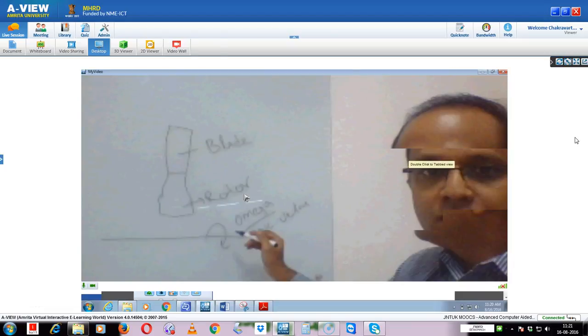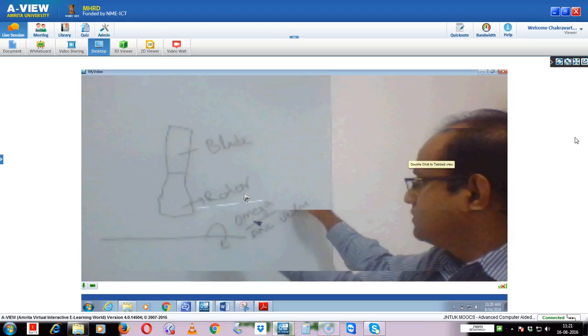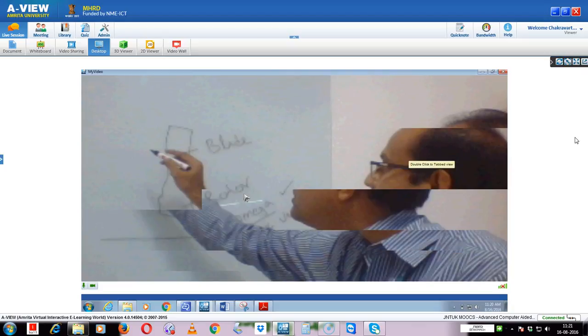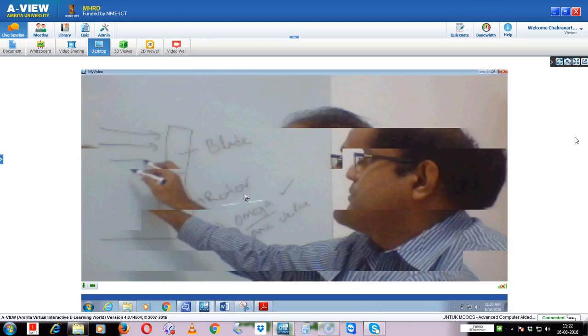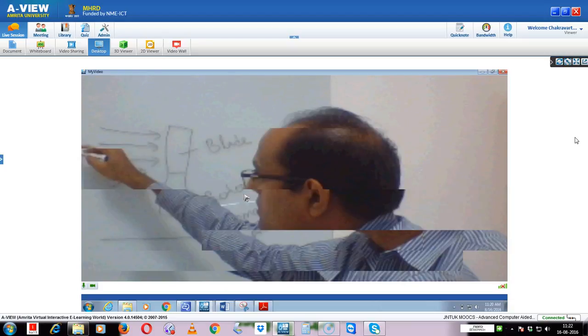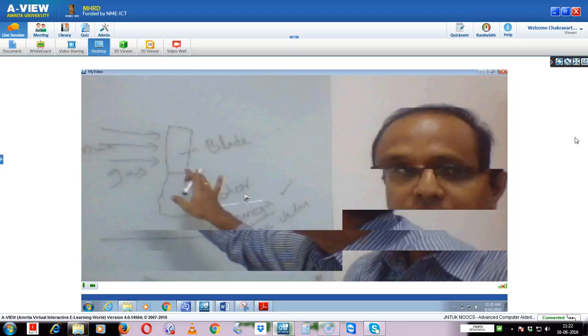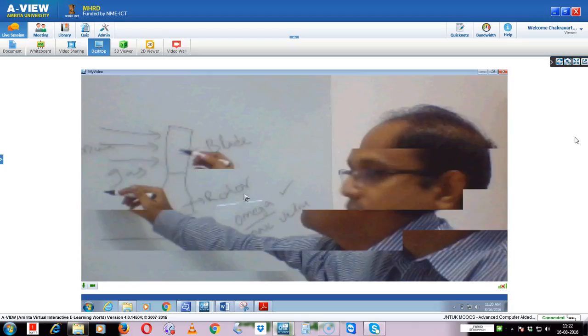So it is angular velocity. This is uniform. And the blade is subjected to pressure load. So pressure load coming from the gas path. This will be calculated as a pressure load. So the pressure load is uniform. This load will be acting throughout the 360 degrees. So the pressure load is also uniform.